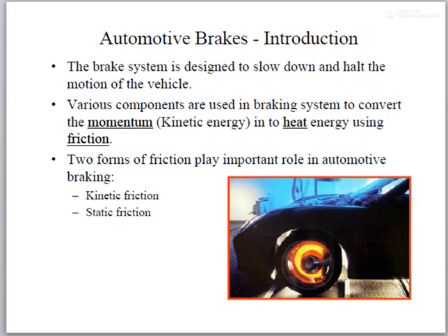Whenever it reaches 20 kilometer per hour, for example, the example which we took previously, a vehicle at 60 kilometer per hour which we need to bring down to 20 kilometer per hour, till that point, until it reaches 20 kilometer per hour, we are supposed to apply the brake pedal, and the kinetic energy of that much amount gets converted into heat energy.